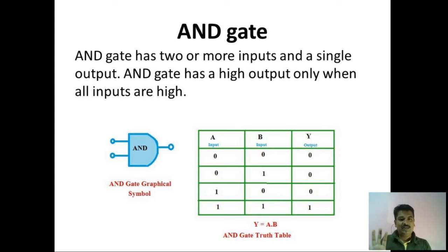And we have a truth table here. What do we mean by a truth table? The truth table contains all the performance of the logical circuit. It contains input values and the corresponding output values: the values of the 2 inputs A and B, and the corresponding output value Y. Also here we have to understand what 0 and 1 mean. 0 in the truth table means low voltage state, and 1 is represented as a high voltage state.